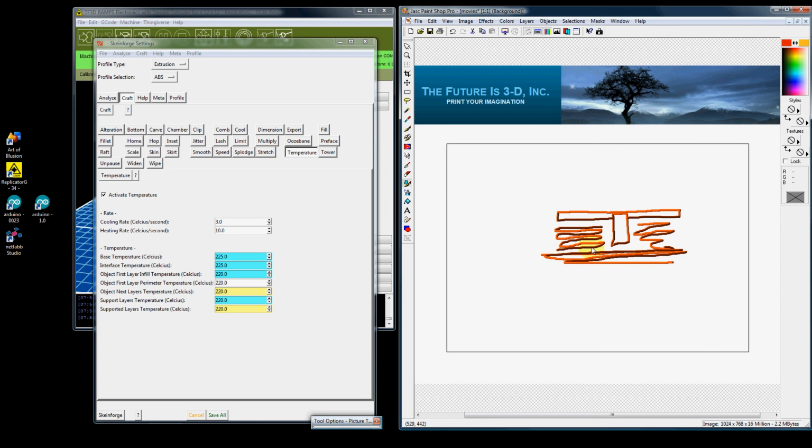So what happens is when it's doing this layer right here, it's going to print support material, and then if you've got a different temperature, it's going to sit here and orbit until it hits that temperature. So you could be spitting out plastic, and then when it starts to print it, it's such a small area that you don't get a good layer. You get just a spotty layer. So keeping these the same, it's going to print that support material, it's going to print your object, it's going to print the support material, and it's not going to sit there in orbit. Now, there's probably a reason for doing this, but it just doesn't work. From what I have found, it also wastes a lot of time. And I've had no problem breaking away the support structure for something like this.